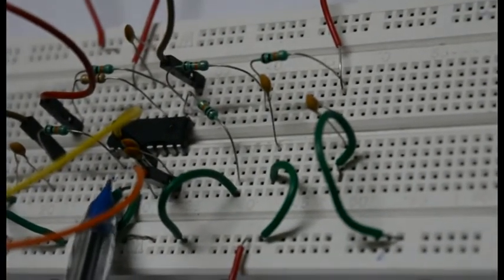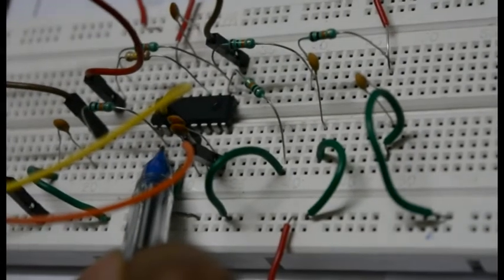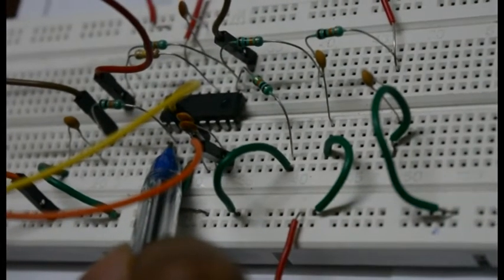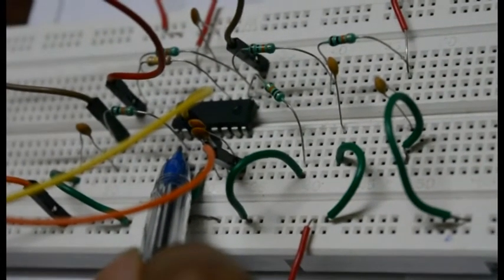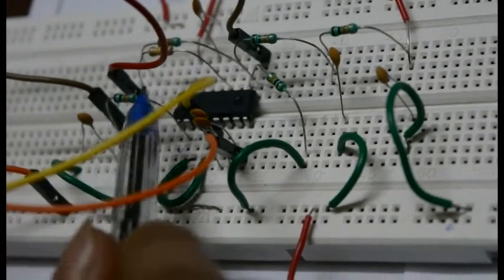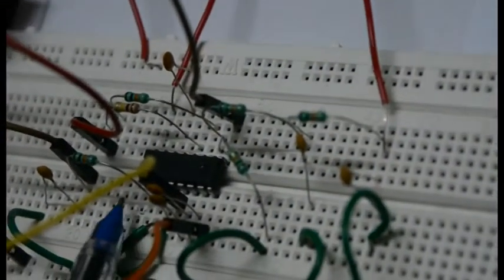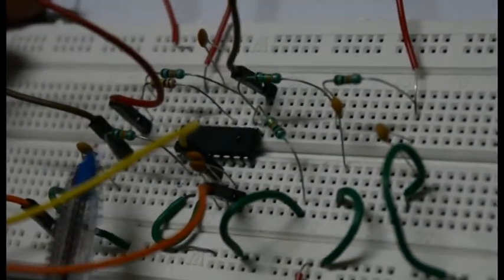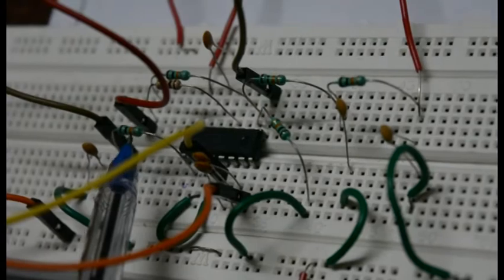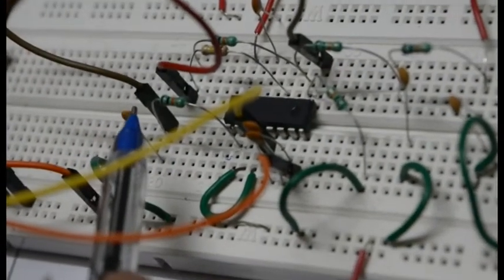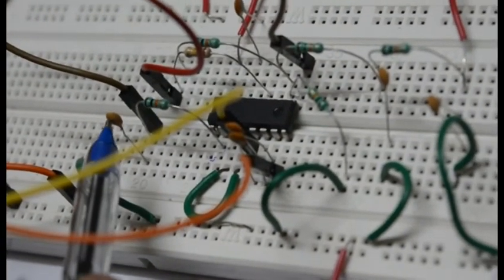The capture range, that is the frequency range up to which the circuit will work, should be very high. So we choose a low pass section connected between pin number 2 and 9 in such a way that we get capture range very high. We choose resistance and capacitance of the low pass filter as 10 kilo ohm and 0.01 microfarad.